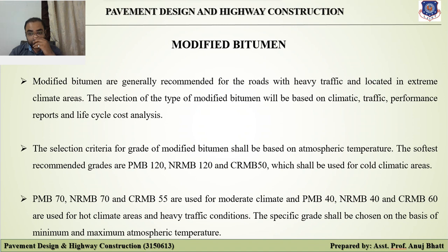The softest recommended grades are PMB 120, NRMB 120, CRMB 50, which shall be used for cold climatic areas, whereas PMB 70, NRMB 70, and CRMB 55 are the grades used for moderate climate condition, and PMB 40, NRMB 40, and CRMB 60 are used for hot climate areas and heavy traffic condition.